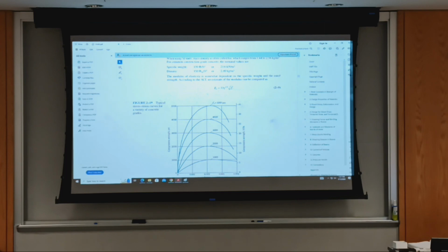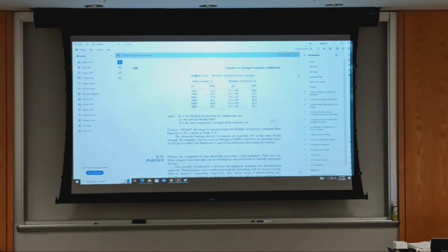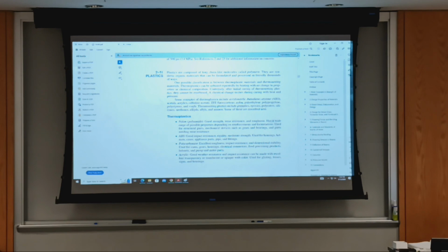More cement in the aggregate mix gets you stronger grades, depending on where it's used, so you improve strength if you add cement. If you add water, you lower it. You need to minimize the amount of water. Sometimes they use air to homogenize it and make it fill the mold when it's poured.